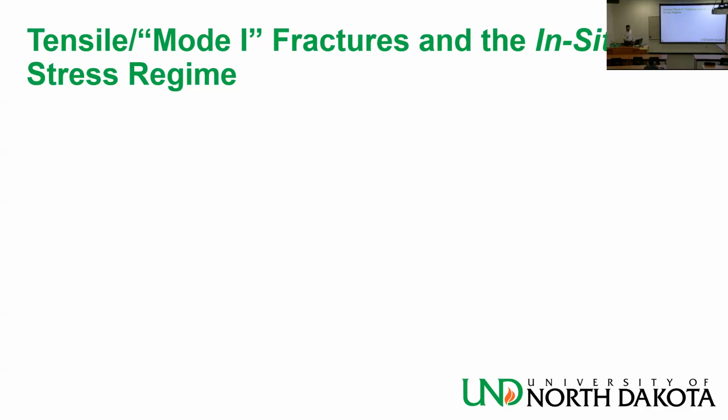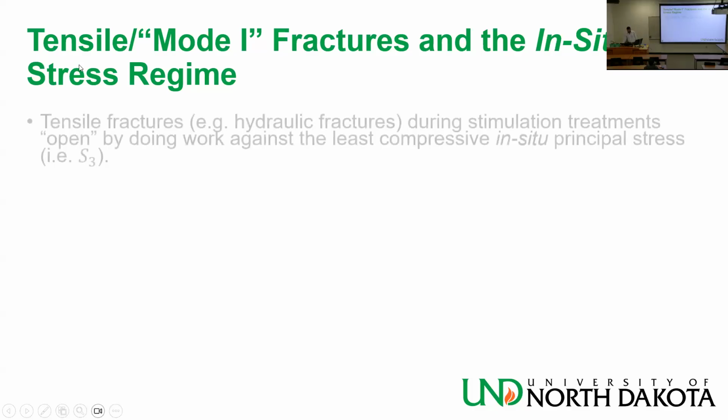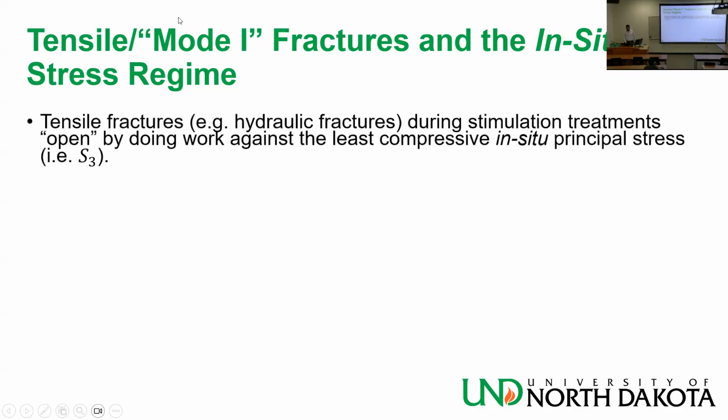Now, I want to do the same thing for the near wellbore stresses, okay? I want you to think of sigma RR, sigma theta theta, sigma ZZ. So we will see now that tensile fractures during stimulation treatments open by doing work against the least compressive in situ principal stress.